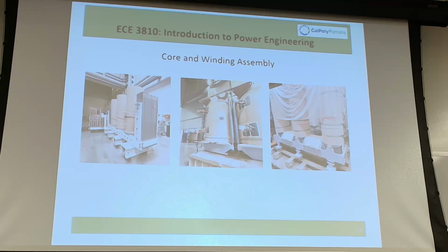When we talk about the flux and how the flux is managed inside the core, we'll go through those concepts. I'm going to remind you of the importance of making the core so precise that you don't even have little laminations, one larger than the other. You've got to be precise. If you put your hand like this, you don't feel it, because if there's one, you're going to cut yourself. They're extremely, extremely sharp.